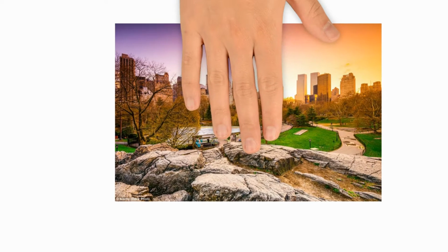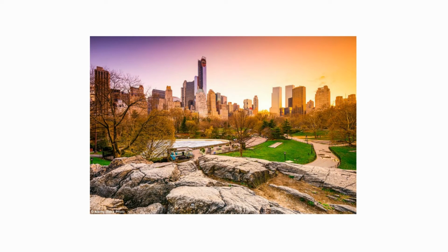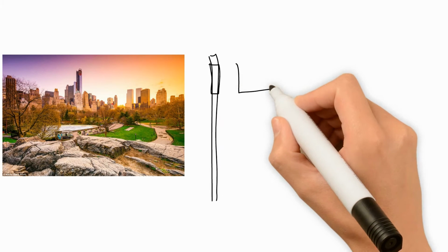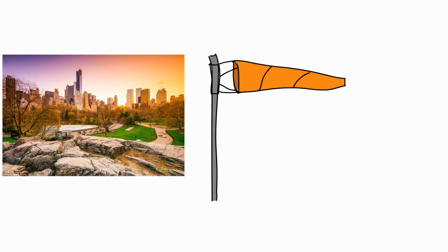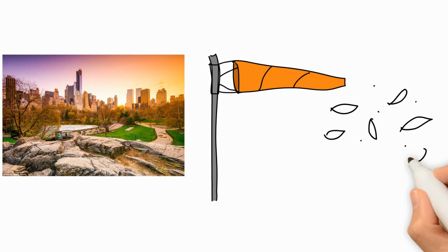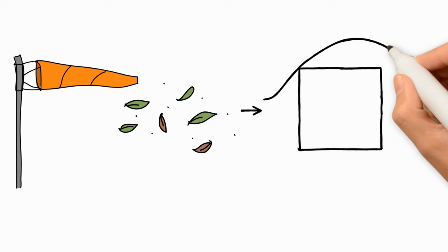In Manhattan, hard marble rock is found at shallow depths. This provides an ideal founding condition for the tower. The core and frame footings bear directly onto the rock, with anchors drilled 26 meters deep. A tower this slender will not be capable of resisting the wind loads without special measures.